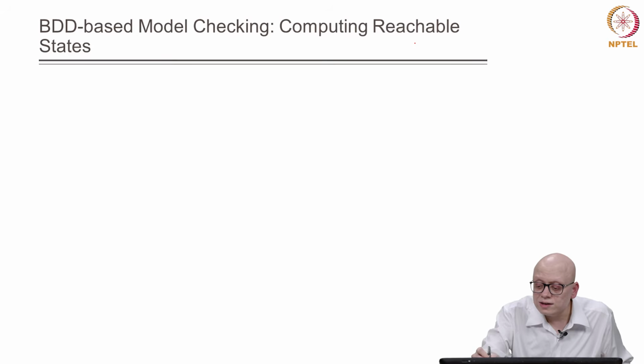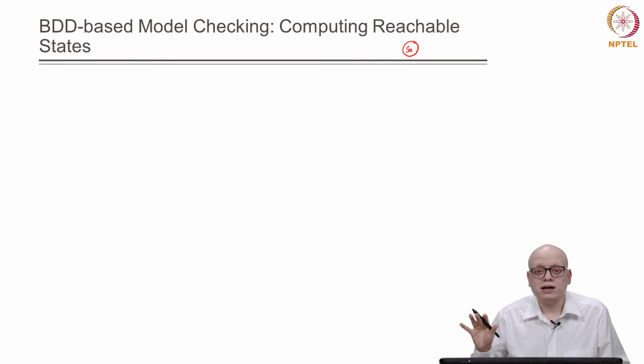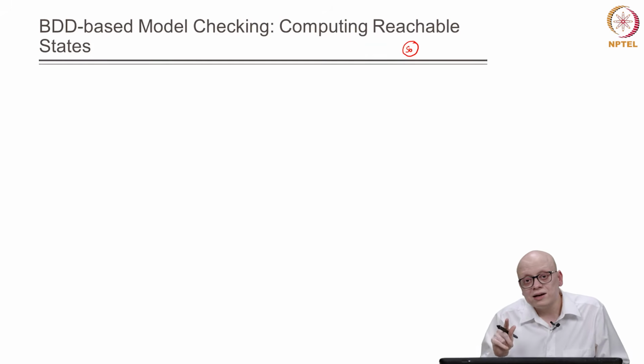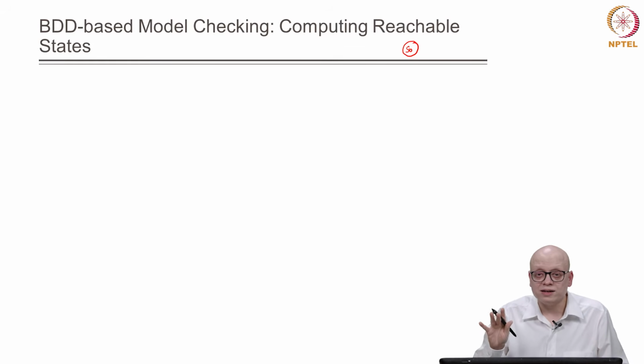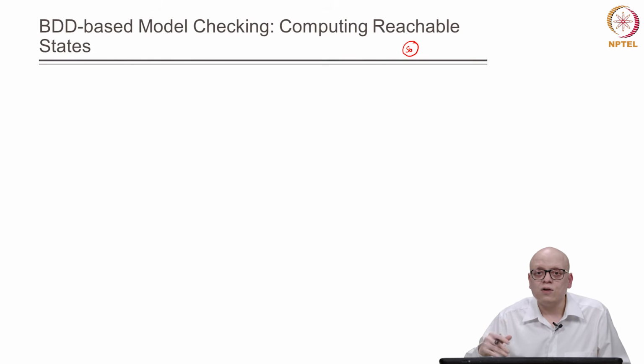Suppose we are given a set of states S0. Then the reachable states are those which can be reached in any number of traversals. Image computation was related to only one step, but when computing the reachable set of states, we are removing that constraint. So, reachable states are those which can be reached from a starting set of states in any number of traversals of the FSM.